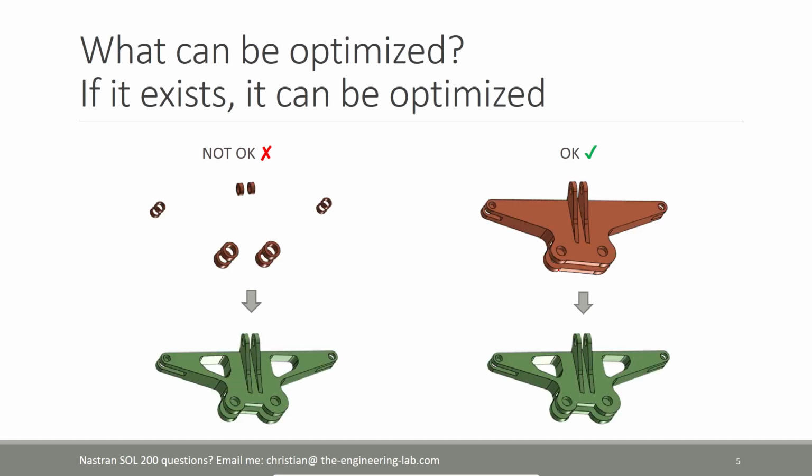Here's another example, just to hammer this point home. Here on the left, the most you have in this finite element model are elements for where you have the support, these cylinder-looking objects here. There's nothing in here, so there's no expectation that the optimizer will automatically start filling in material for you.